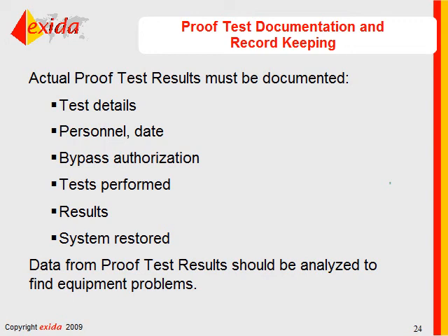So there are some situations where you may want to perform a proof test of a device while your unit is running. In that particular case, you need to temporarily bypass the safety function, because if you are, let's say, playing with a transmitter to perform various tests, then you may end up getting a wide range of process values, quote unquote, as an input into your logic solver. You may not necessarily want to trip on that. So that's what the bypass authorization goes for.